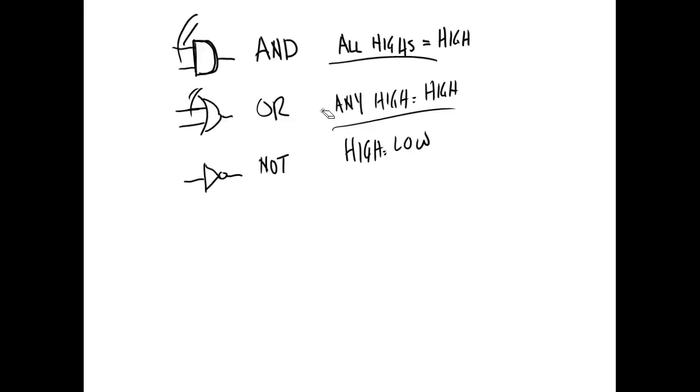So every gate is given a math expression. If you can set up an equation for a circuit that you come up with in your head, and then the equation reduces, what that means is the size of the circuit just did what? Reduce, which is what's so cool. So it allows you to reduce circuits. You can come up with a circuit in your head, then develop the Boolean equation for the circuit, then reduce it.